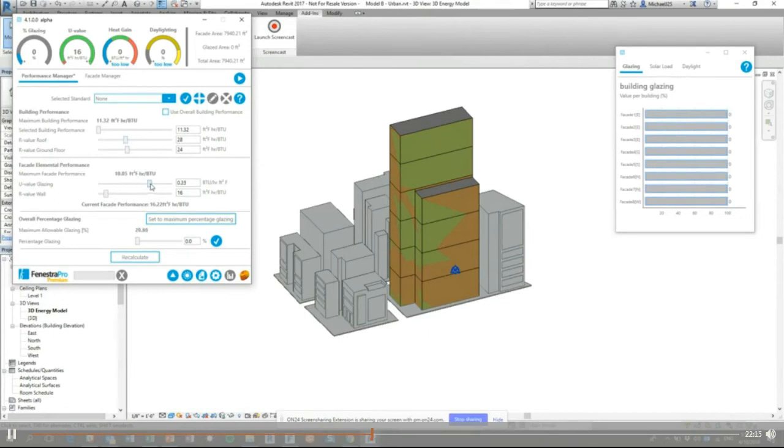If we start then setting thermal performances for our glass and our walls, you'll see my glass to wall ratio change. So again, high performance glazing, we can figure out how to use more glass. Poorly performing glass, our glass to wall ratio is limited. So we can very much play around with these values to optimize our solution, our glass to wall ratio.